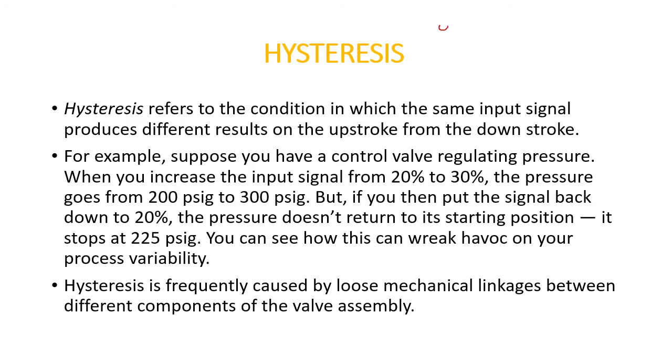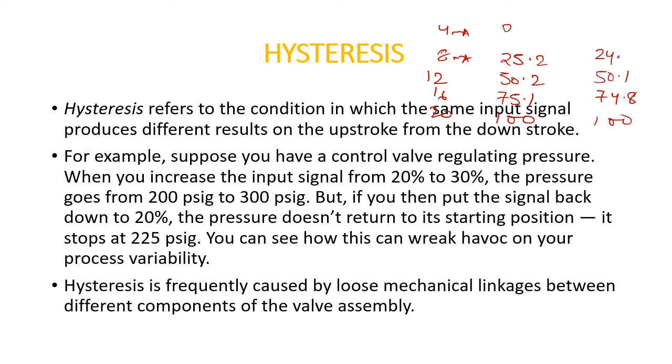For example, if you give a signal of 4 milliamps, 8, 12, 16 and 20 milliamps, and say the valve opens 0%, then 25.2%, then 50.2%, 75.1% and 100%, but when it is reversed, this is 100 but this is 74.8, this is 50.1, this is 24.1.